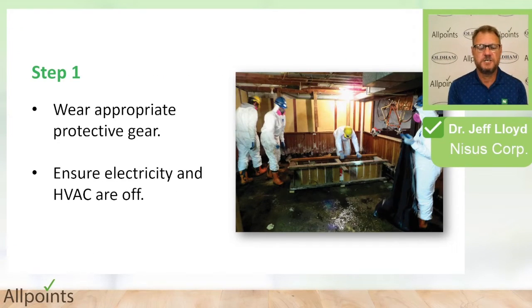So step 1, first of all, make sure the structure's safe. Don't go into a structure if the roof is caved in or if the basement's still flooded. Be careful about how that's pumped out. You don't want the foundation walls to collapse, so it's better to let it subside slowly. So make sure the structure's safe, and then wear the appropriate protective equipment.